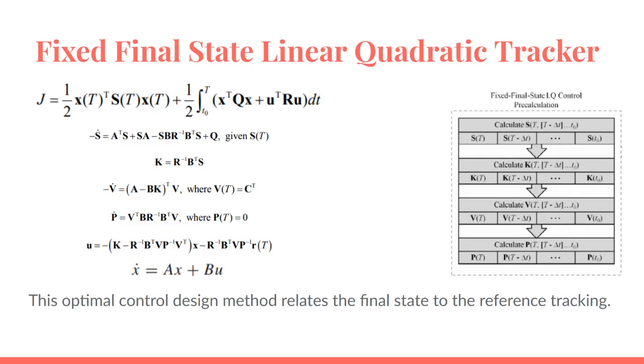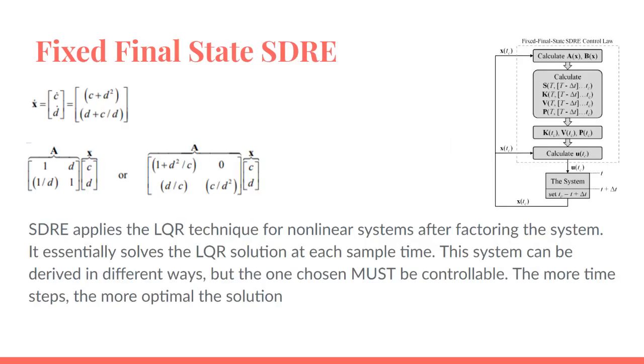So if you're using MATLAB ODE45, it gets a little bit tricky because ODE45 can only integrate forward in time. So once you integrate it, you have to flip the time index around with the variables. And we'll talk about that more in the example coming up.